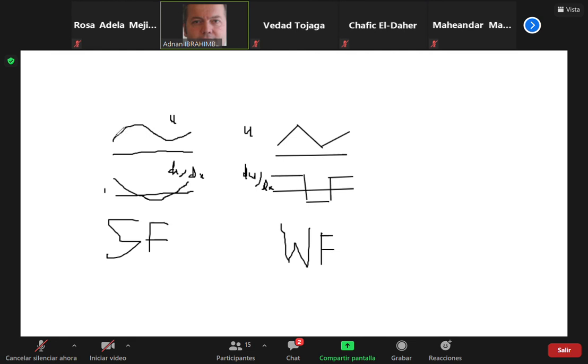If this is the displacement field, I can say that on top of this displacement field, I can apply a small perturbation field, which I can call W. You can notice the W at this point where I apply the support. Here I can say that W of 0 is equal to 0. This is the idea of kinematic admissibility. And at any other point, I have this variation.